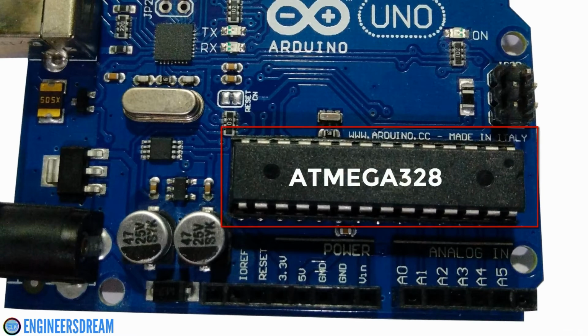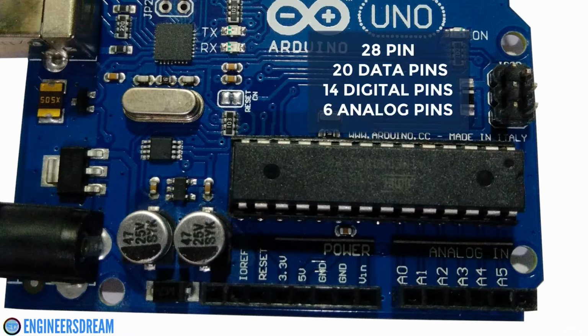Next, let's talk about the Arduino microcontroller board. The Arduino Uno consists of an Atmega 328 microcontroller. The Atmega 328 is a 28-pin microcontroller, out of which 20 pins are data pins. Out of these 20 data pins, 14 pins are digital data pins and 6 pins are analog data pins. We can use the data pins either as input or as output.